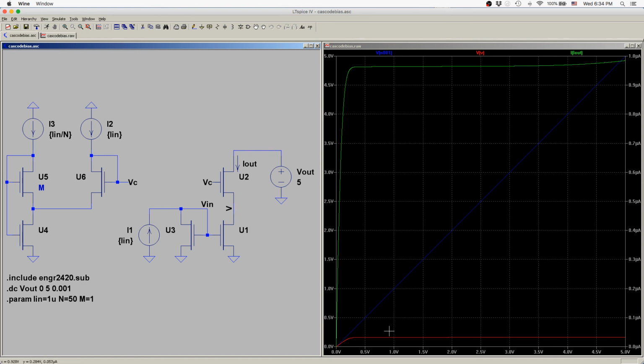You can see that it's down at about 0.15 to 0.2 volts, so that's pretty much a saturation voltage above ground for this particular current level. And we can see what the cascode bias voltage is. It turns out it's about 1 volt for this current level. And there is no visible place where we have that kind of intermediate slope with a kink in the curve where it flattens out.